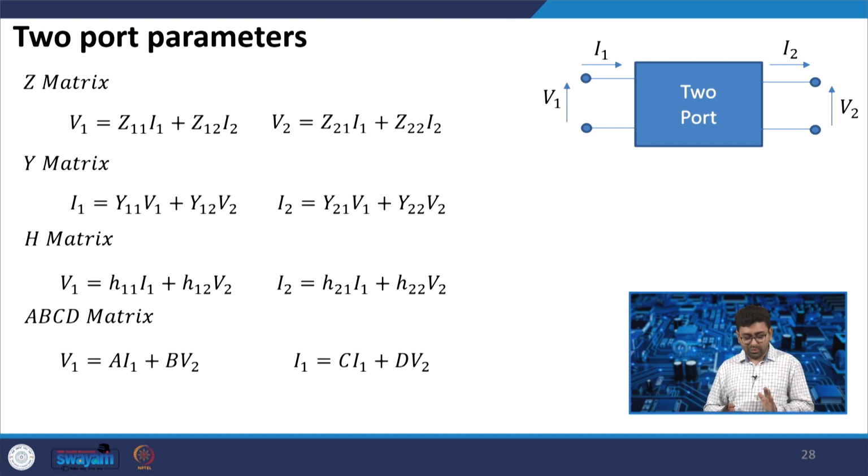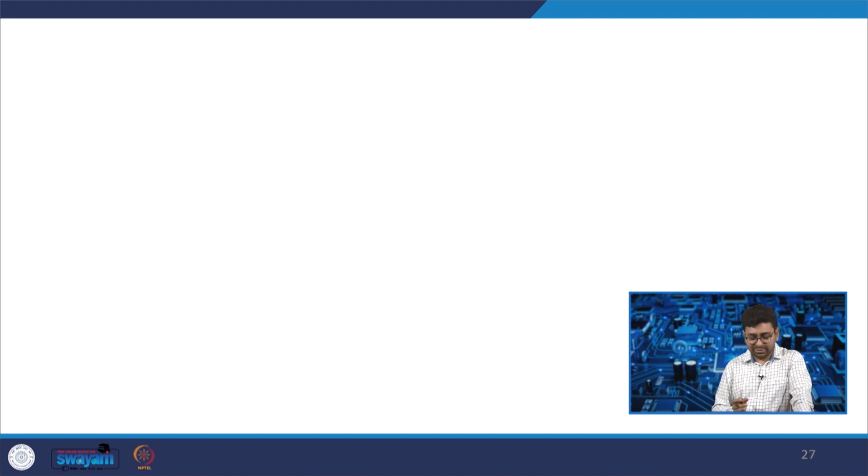Now we will move on. We have already discussed most of the things related to the transmission line. Based on the understanding of the transmission line, whenever you try to connect any component at high frequency on chip, or even when you are designing a PCB for RF component measurement, you should keep in mind the effect of the transmission line, and if there is a mismatch you need to match the impedance. Otherwise there is more reflection, and by using the reflection coefficient you can find out how much reflection will happen. By using the transmission line voltage and current equations you can also find the different phase at each stage.